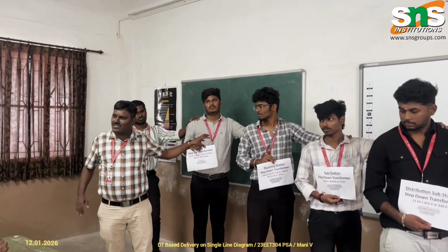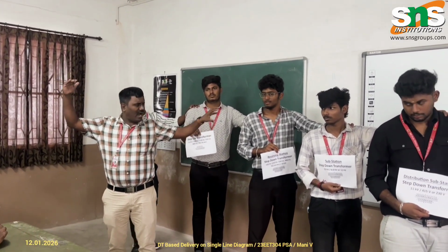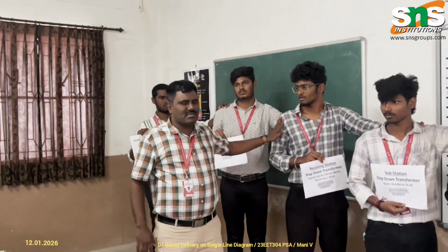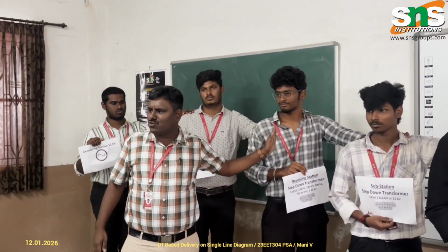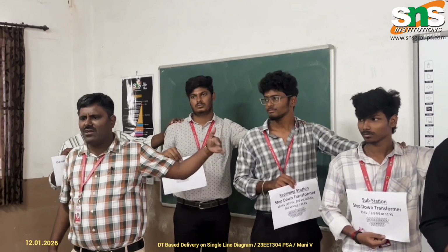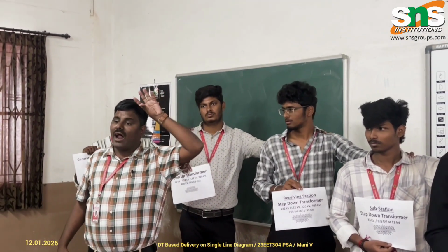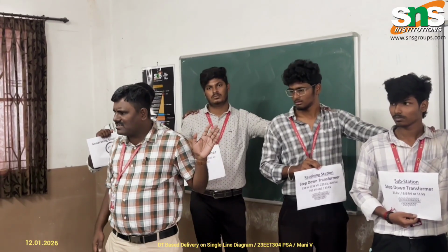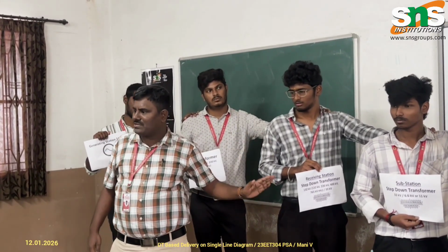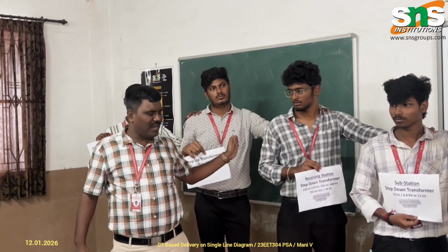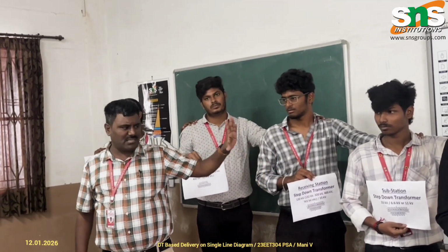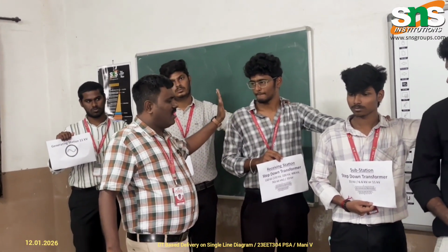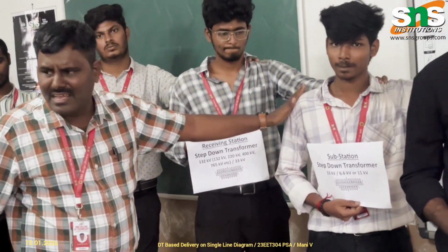The primary level of transmission is ultra high voltage, and the next level, secondary transmission, is extra high voltage level. Now the receiving station receives either 132 or 220 or 440 or 765 kV, whatever it may be. The ultra high voltage is stepped down from the maximum value to 33 or 66 kV. Then it transmits the voltage from the receiving station to the substation.